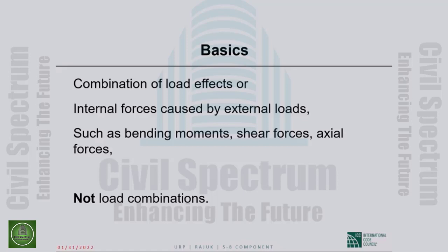Those bending moments due to dead loads, live loads, wind loads can be combined. Those shear forces due to the various loads can be combined. And that's what we do in design. We combine load effects, the internal forces caused by the loads, the bending moments, the shear forces, the axial forces. We do not combine the loads. Okay, so combination of load.